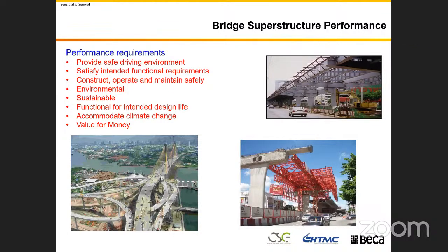I think I have a question, Rohit. Yes. I'm Ravindra here. Very often people come and ask us to construct seamless pavements over the bridge. Like in your bridge structure, you have a run-on slab, and our pavements come and stop ahead of the run-on slab, and we anchor the pavement, stopping any longitudinal strains coming along the road getting transferred to the bridge deck, right?